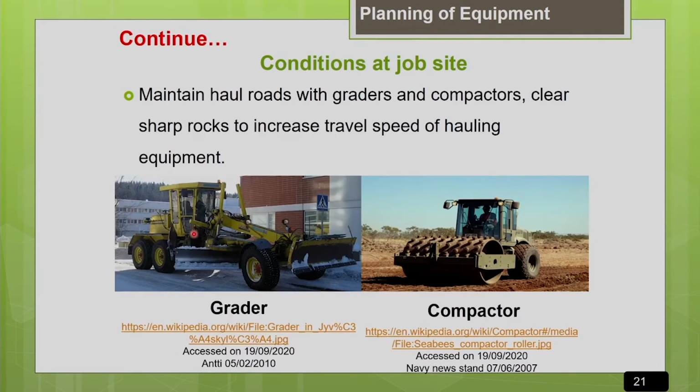Another important guideline which we should keep in mind is we should always maintain the haul routes. The haul road you have to maintain. There are so many pieces of equipment to maintain the haul road, like either you can go for a grader or you can go for a compactor.